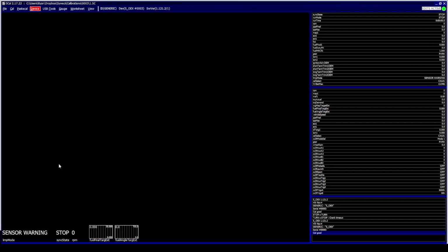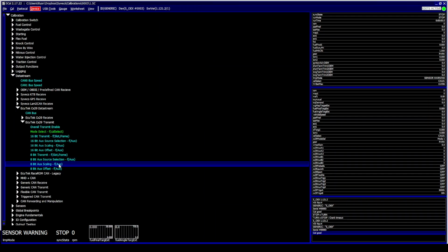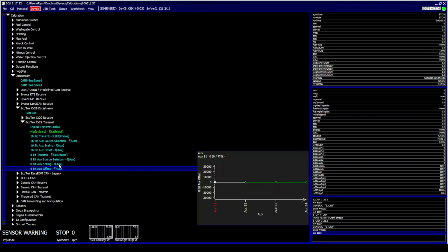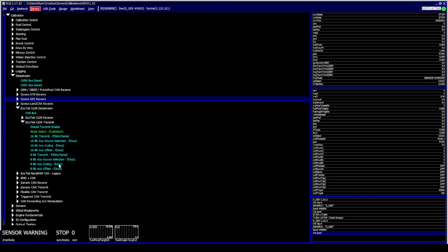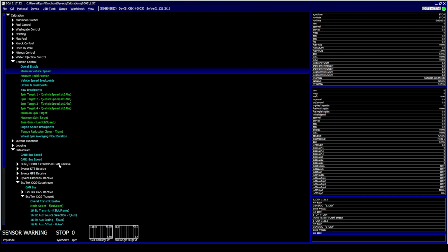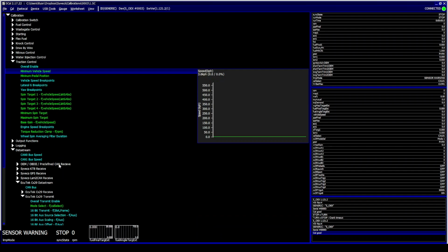If you want to send the limp mode up, you can do that as well, and you can scale that to suit. Now, one other really cool thing that you can do with the OEX with this latest software: we obviously communicate with the factory car's CAN bus by connecting to the original car CAN. And from that, we pick up the wheel speeds at an extremely fast rate from the ABS module. That comes into the OEX, and then you can use our traction control strategy that is famous in our plug-and-play kit in the OEX.